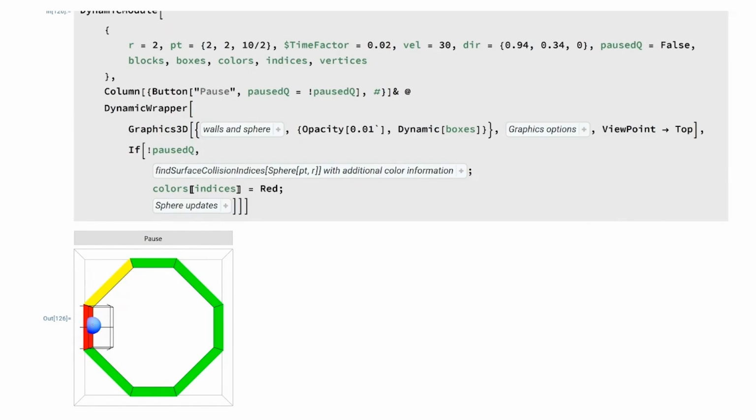And then all we have to do is look up in this basically lookup table, which surfaces are nearby. And so in this example, the nearby surfaces are colored yellow, and then we do the harder calculation of where the hits actually occur. And so that's this red surface. So we basically excluded 99% of all of the surfaces and objects with a very, very fast lookup. And then we do the hard thing later.